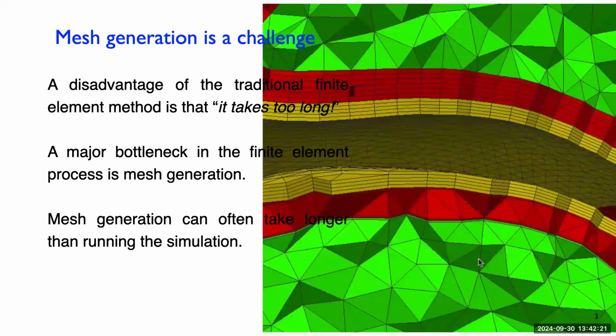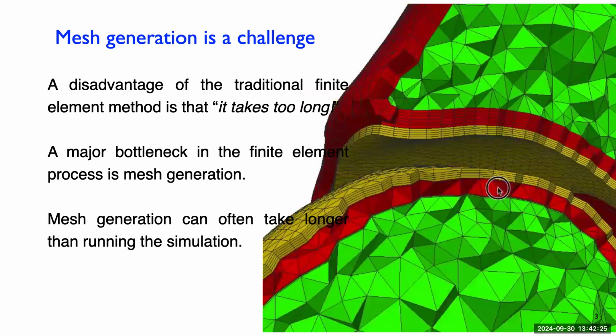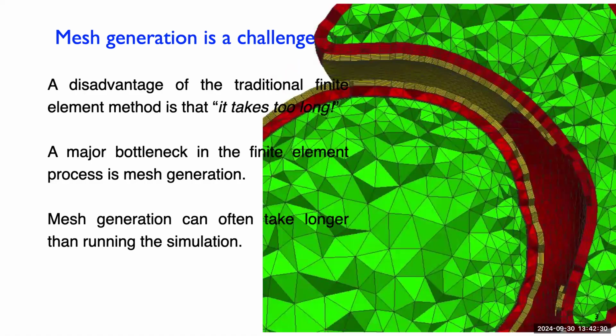So I looked at loads of different ways to make meshes of complex parts, accounting in this case for cortical bone and calcaneus bone, different stiffnesses, cartilage, varying thicknesses, and all these different element formulations. And then you make certain element types, and you bring it into the software, and it just wouldn't converge because they weren't well formulated. They were poor elements. So it's a real pain, and it's a major bottleneck in finite element analysis.